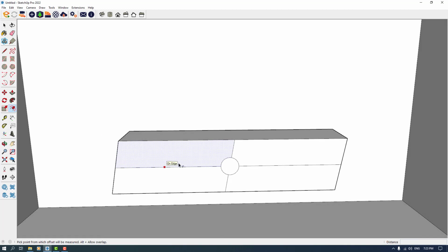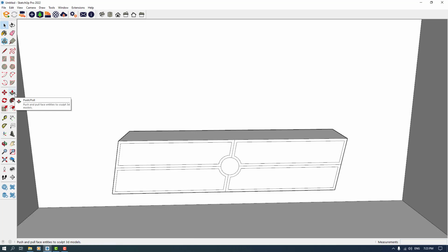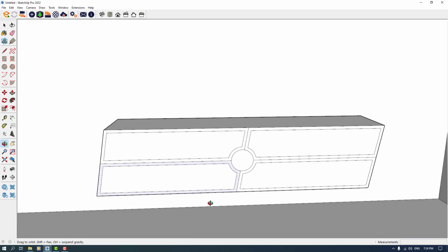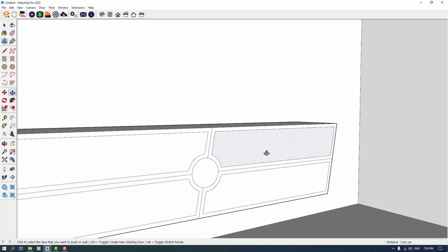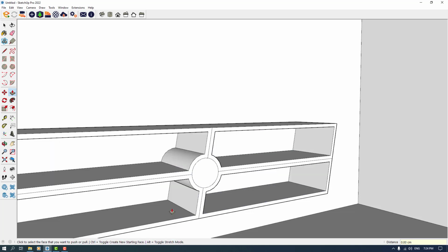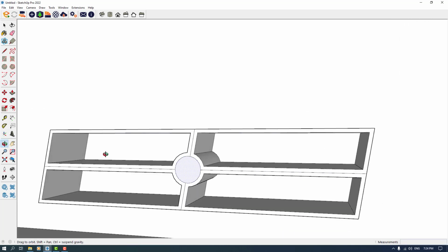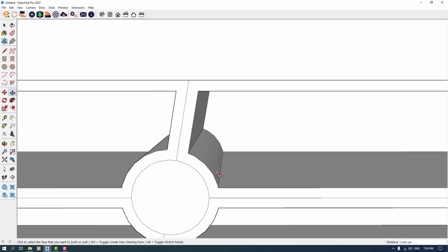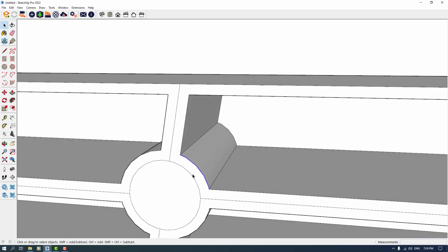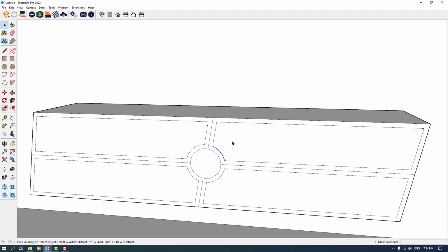I use the offset option, and I want to offset my TV wall something about 1.6, 1.6 and 1.6, like that. And now I'm gonna push them down with the extrude option, something about 28 centimeter for each side. And now I think everything is good, but these places are not very smooth, I'm gonna Ctrl Z.